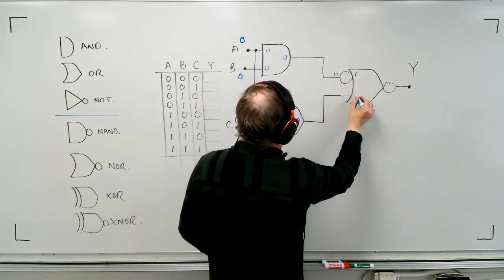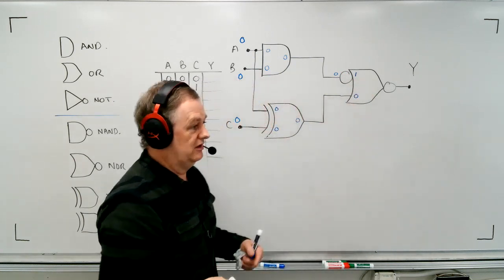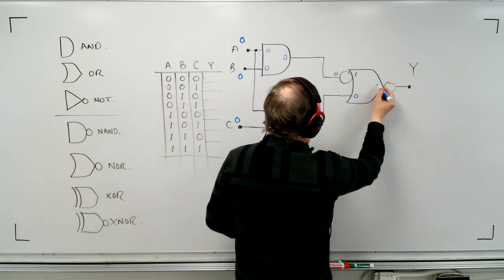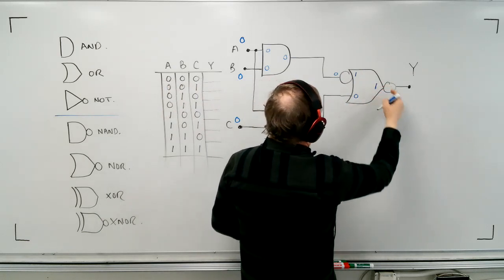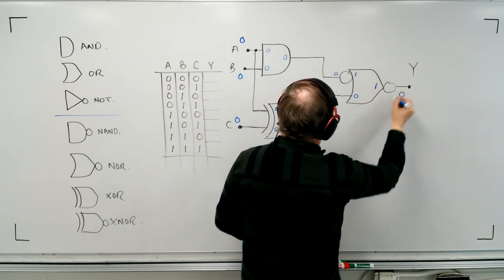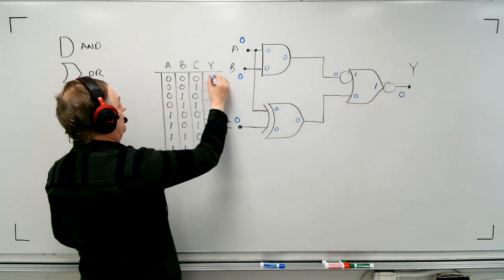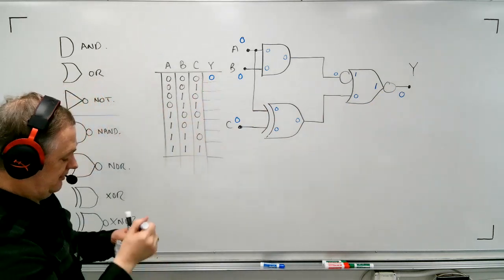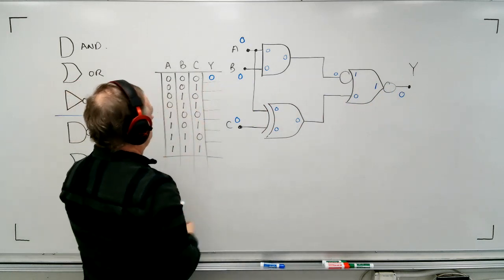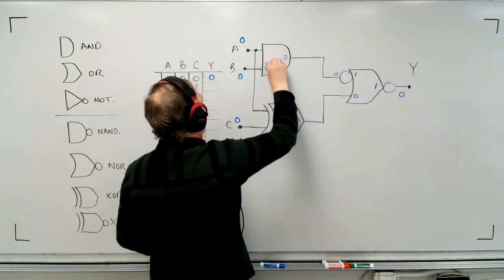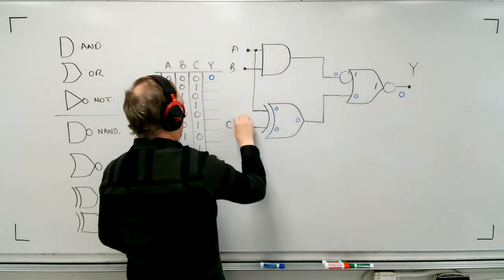This is a 0, and it just goes in there as a 0. Now, what do a 1 and a 0 do with a regular OR? Well, this exciting stuff, they make it a 1. But you've got an invert which says, no, you're going to be a 0. And so our first output condition for the first set of circumstances is actually 0. Now be patient and let's carry on to the next condition.